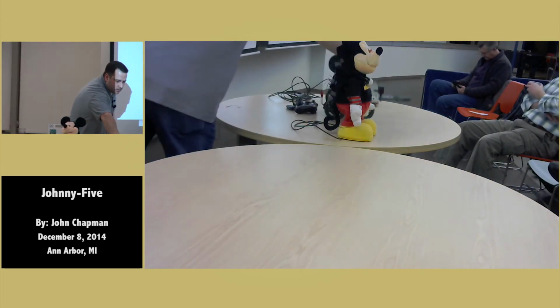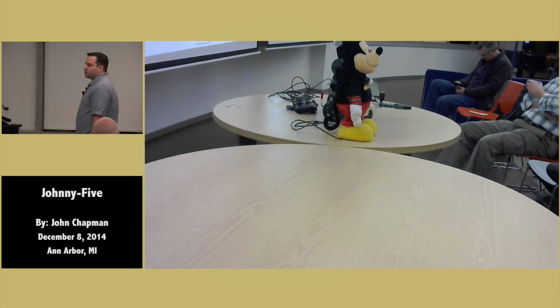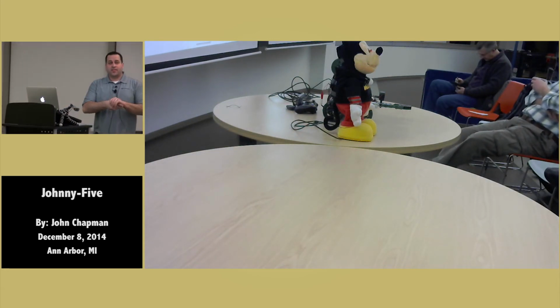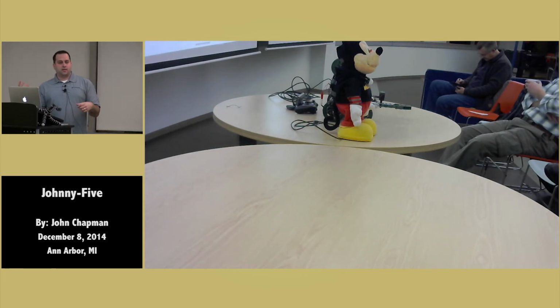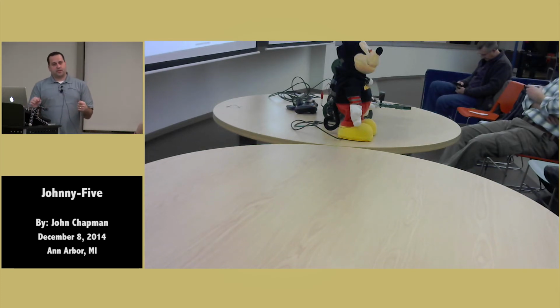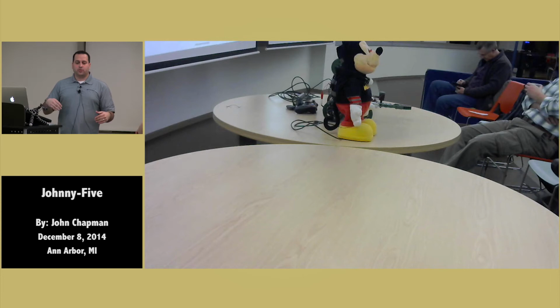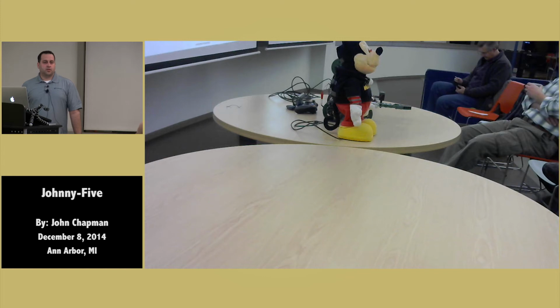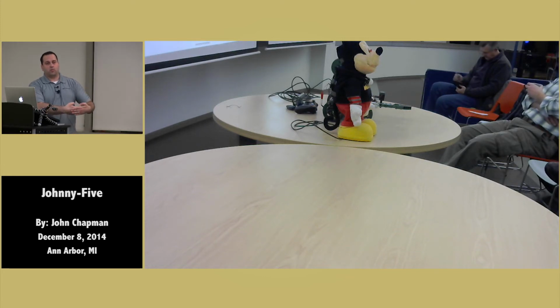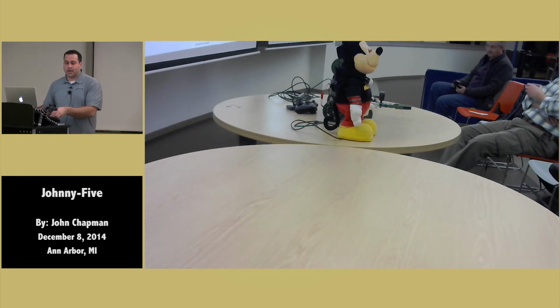Yes? So everything kind of has issues, right? One of the things I really like is taking a Raspberry Pi with an Arduino, and you can connect serial connections between the two of them. That as well has issues. If you want to do pins directly for the serial pins, natively the Raspberry Pi is going to use 3.3 volts for its serial connection, and the Arduino uses 5 volts. So again, how do I synchronize those two voltages? To simplify that, I actually use a USB connection between the two, and then that's always going to be 5 volts over USB. So if you just put the two together on one board, you can have an all-in-one solution, meaning no separate computer running it.